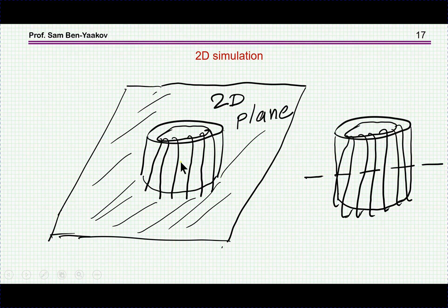This core goes both ways, up and down, so that the edge effect is farther away and not affecting. Obviously, this is not exactly the shape of a common core, although there are some cores like this, especially if you stack together a number of toroids. But for the sake of understanding the phenomena we are talking about, I think this is okay.